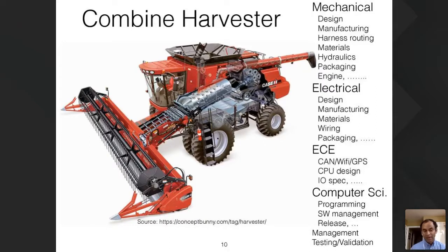So basically what a combine does is that for different crops, there will be different headers to cut the crop. It cuts the crop, gathers all the cut crops to the center of the combine and feeds it inside. For example, let's say you're harvesting wheat. It will cut the top of the wheat and put it on a conveyor belt going from the side to the center. Then it's all fed into this conveyor that feeds the wheat grains with everything, the whole wheat chaff.